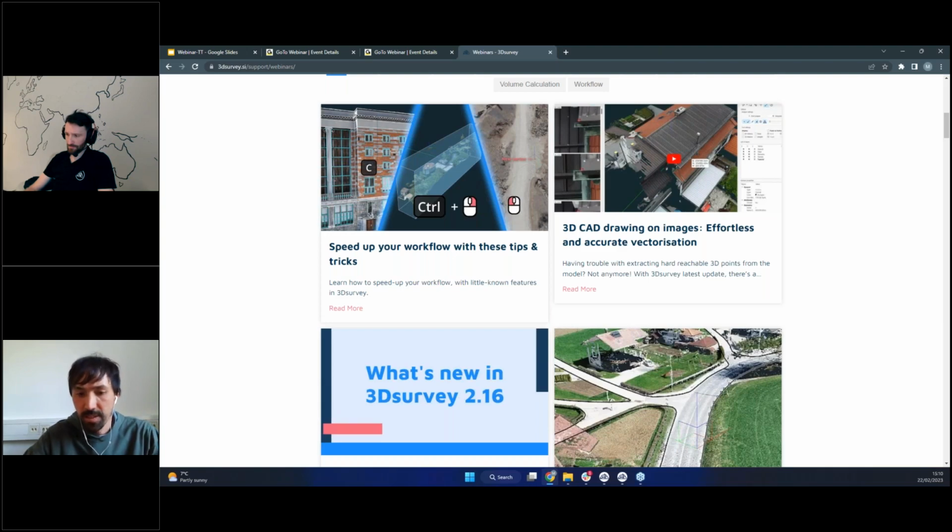If you would like to have the best one, it always helps to get at least one circle around the building. So if you do the main mapping at 80 meters, then do circles at 60 meters with the side camera around the building. In this way, you will get the best 3D model.